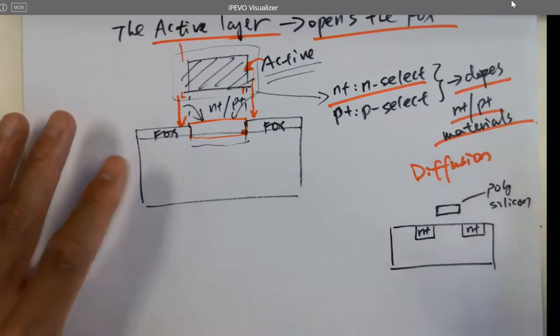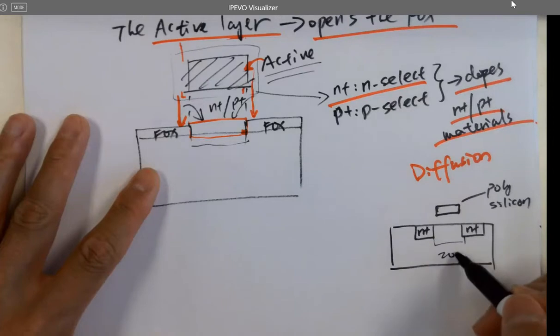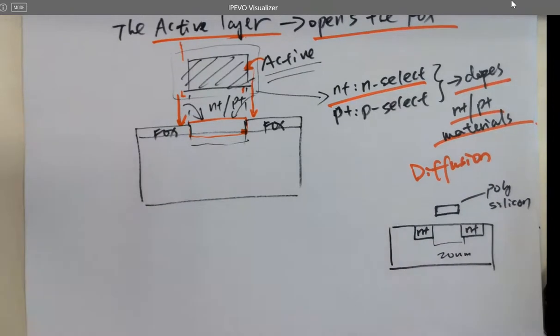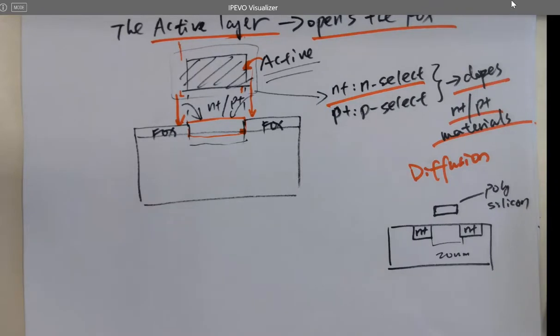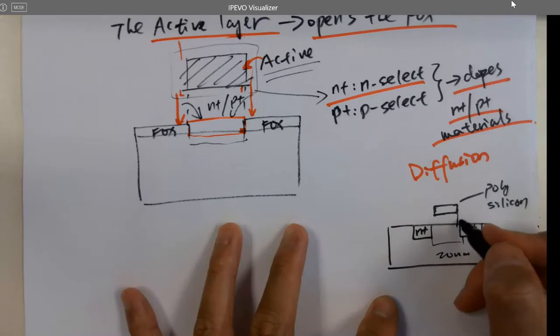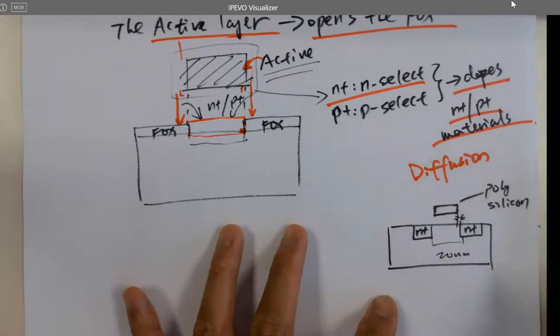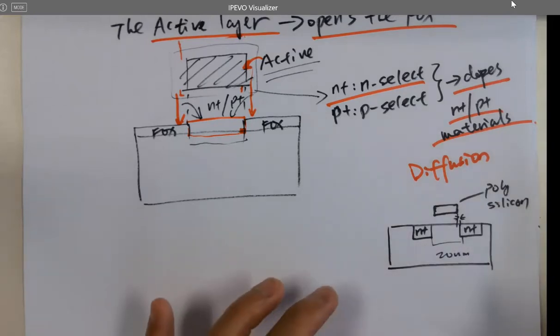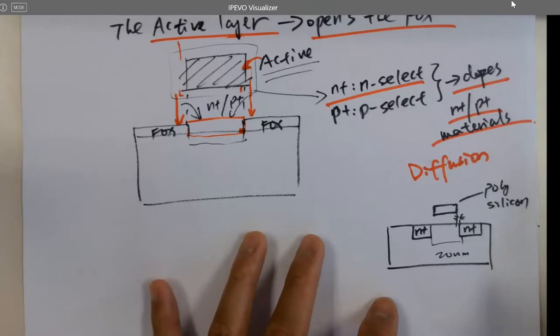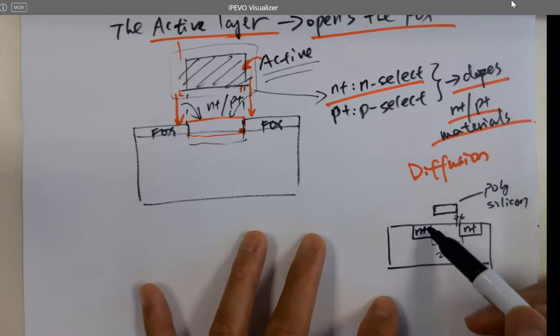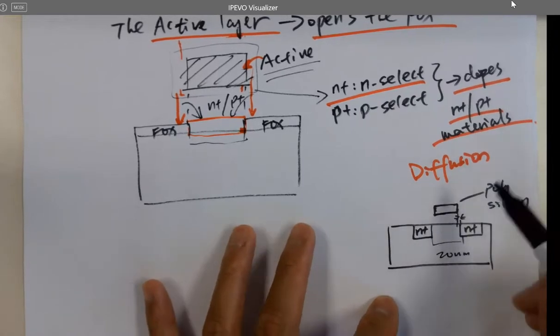I mean, whenever the channel length is down to like 20 nanometers, the N plus is only 20 nanometers. And I think you can align it precisely enough to have the gate directly on top of the channel without any misalignment here. Well, I mean, make it big enough and you won't need to worry about this one, right? But the point is to make it small. Good point.